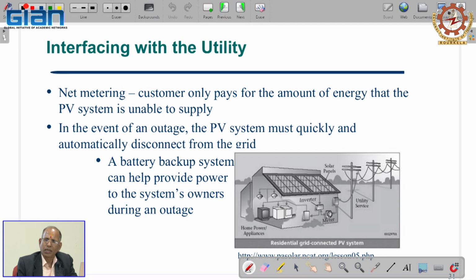How? The PV system can operate with leading and lagging power factor, meaning that they can supply reactive power. During the fault condition, generally voltage drops. For example, if because of a fault the voltage becomes 0.8 per unit, and the PV system can supply power and bring the voltage back to 0.95 or higher, it means things are done.